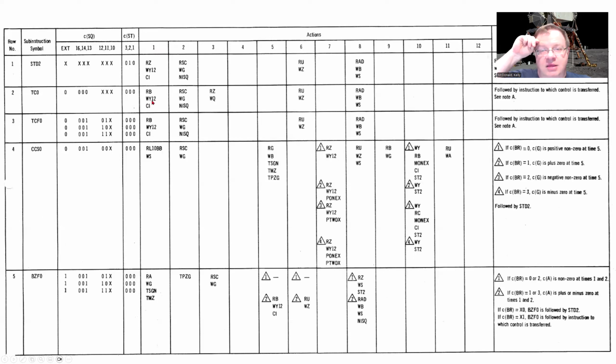So that's data that we will write into the Y register. And in fact, this control pulse writes in the low 12 bits, which is a memory address, right? The 12 bits for a memory address. So we take whatever our contents were in B, we take the 12 bits that we need, which are a memory address component. In this case, the CI is clear a carry bit, so that we're ready for the next instruction.